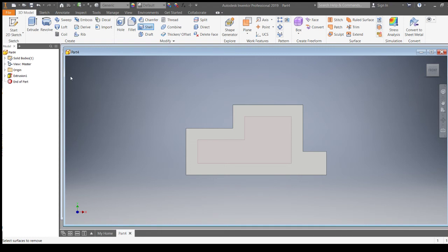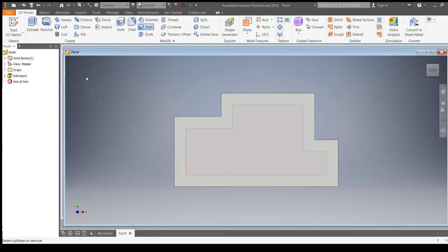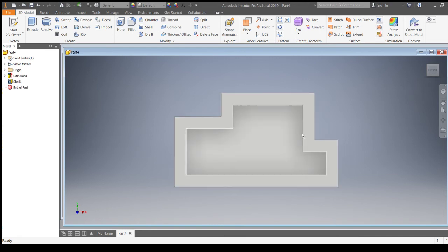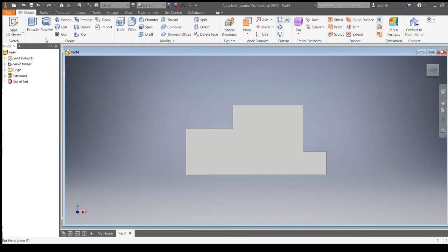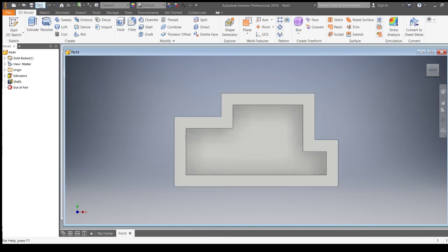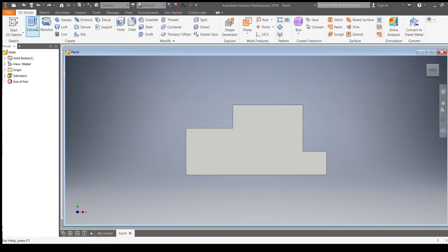Okay, so 5 millimeters. See, the outline has appeared again, that's how we know it's good. Click on the front one. You'll notice it's incorporated now our smallest cube, and that the shell has extended outside rather than inside, which brings our borders out. Hence why when I go back and forth, you'll notice the cube gets larger. Well, it's not much of a cube, it's more of a podium, but that's whatever.